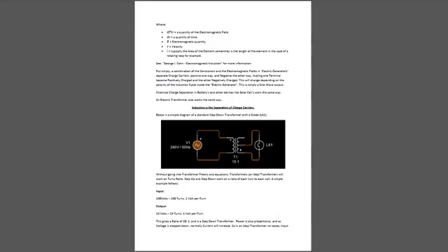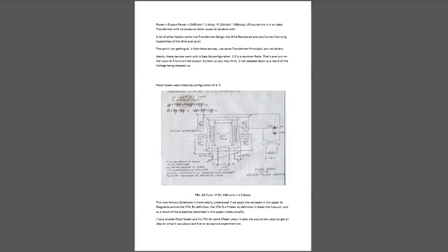Power is also proportional, and as voltage is stepped down, normally current will increase. So in an ideal transformer, no losses, input power equals output power: 240 volts 1 amp, 24 volts 10 amps. Of course, this is in an ideal transformer with no losses or other issues to contend with. A lot of other factors come into transformer design, like wire resistance and also current carrying capabilities of the wire and so on. The point I am getting to is that these devices use some transformer principles, but not others.